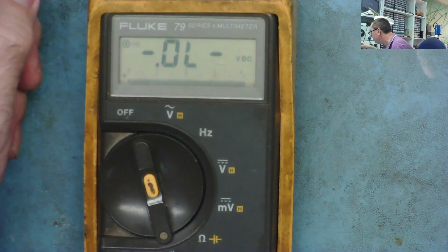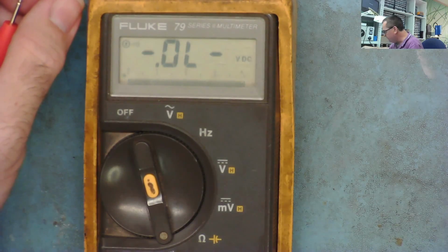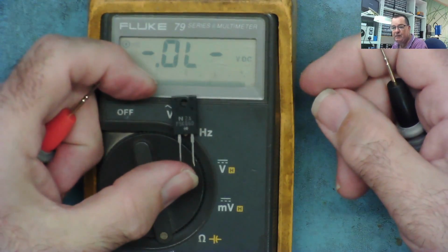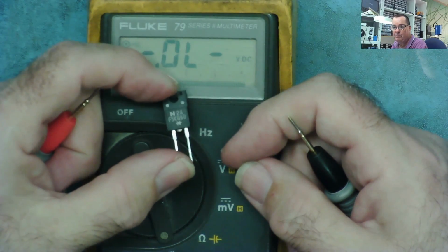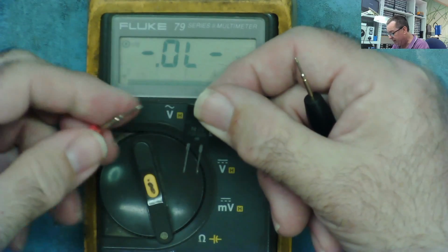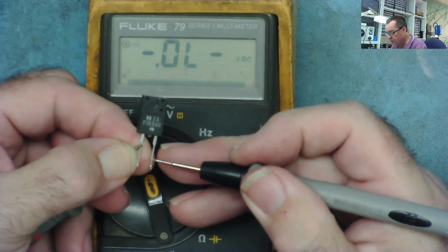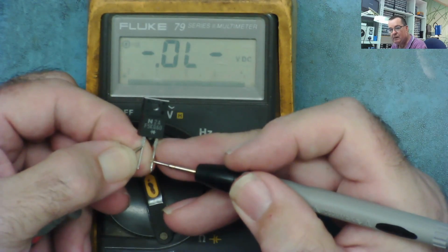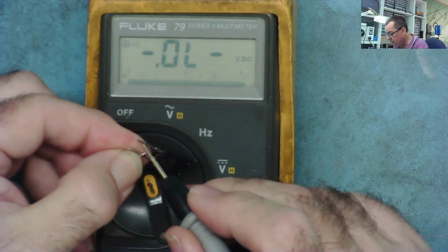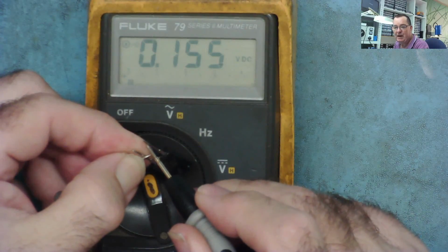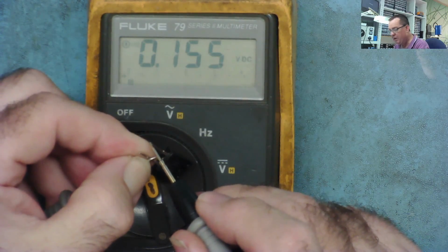We had a few more, so let's look at the other ones we were just looking at. I think we looked at this one, F5KQ60, which I thought was probably a 60 volt and 5 amp. And there's no way to measure that, but you can see if it's any good, and you can see if it's a Schottky diode. So, positive to the cathode doesn't conduct. Go the other way around. Positive to the anode, 0.155. You see that's a much lower forward voltage drop. And if you have stayed awake, you'll know that is a Schottky diode.